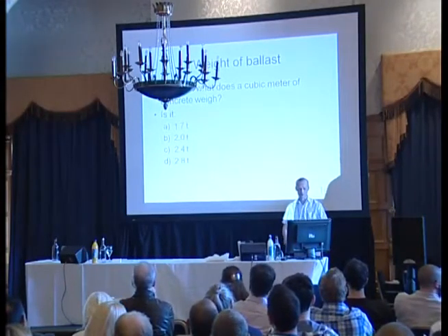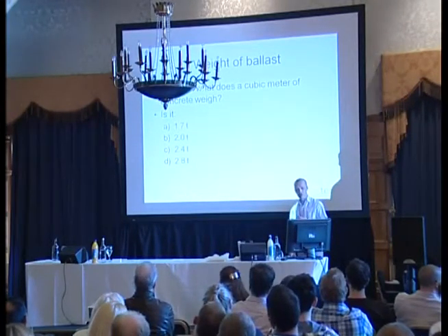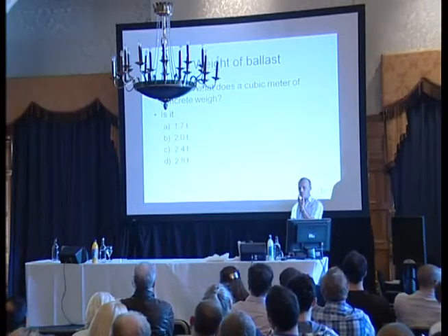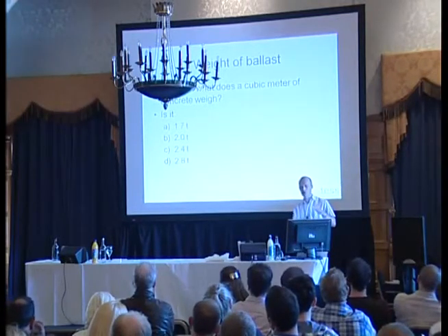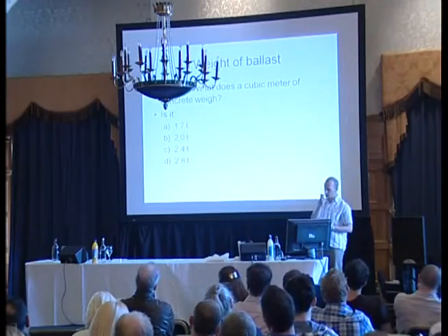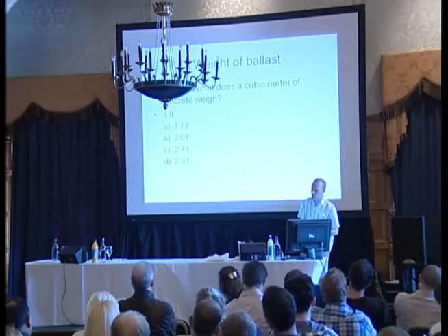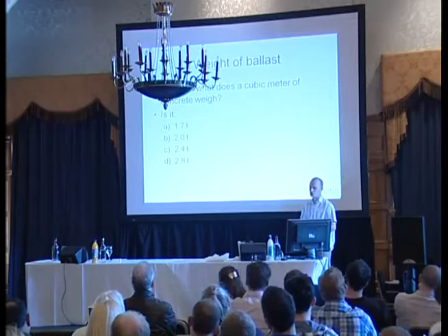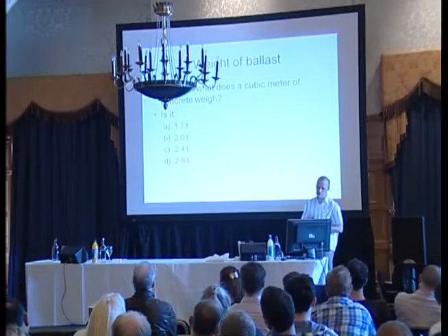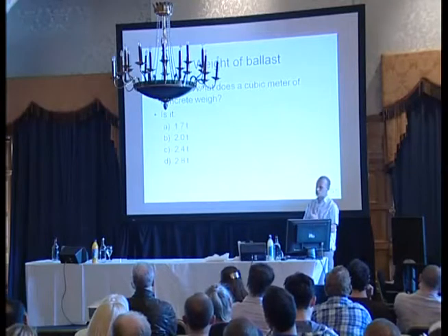Okay. Well, you are right, according to the British standard, the average you use for a standard concrete is 2.4 tonnes for a cubic metre of concrete. That's when it's a full cubic metre, not when it's had all the tops knocked off and the bits taken out of the bottom and all the rest of it. I've been told, oh, that weighs that much, and it's like, well, actually that's not a cubic metre anymore. It's had half the top chopped off because it fell off the back of an artic at some point, yeah? So a full cubic metre of concrete you can allow for on a ready reckoner to be 2.4 tonnes.